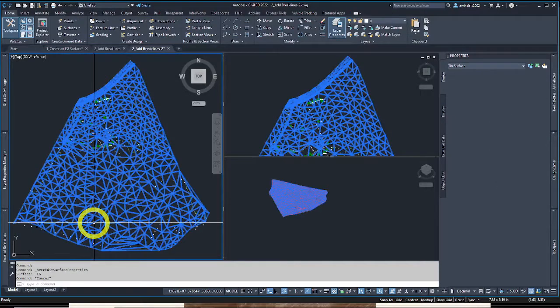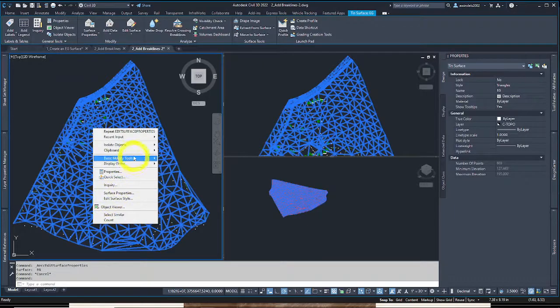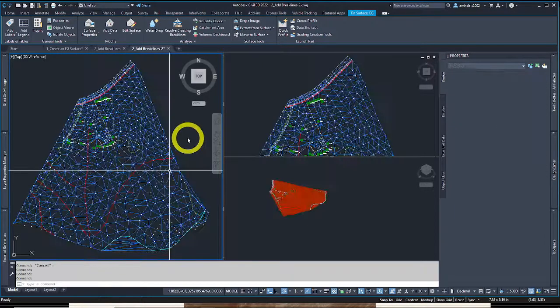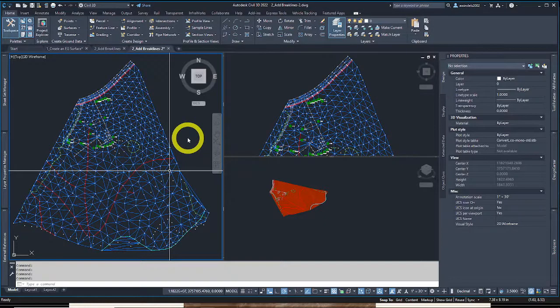Let's grab this surface and right click, and let's send it back. Sends it to the back of the display order. And the default in AutoCAD is that new things that are created get displayed in the front, the foremost, above everything else. That's just the default of AutoCAD. When you copy and paste something, that item will go to the front by default.